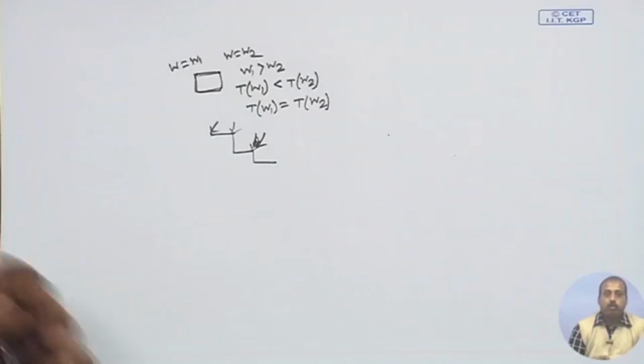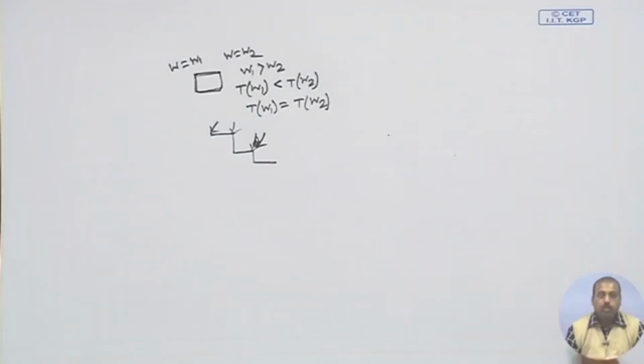This may be due to some functional module inside the core that takes a huge amount of time, maybe some scan chain that is very long. As a result, whatever TAM lines we assign to it, the test time is dominated by the length of the scan chain, and assigning more TAM bits to the core does not help in improving its test time.